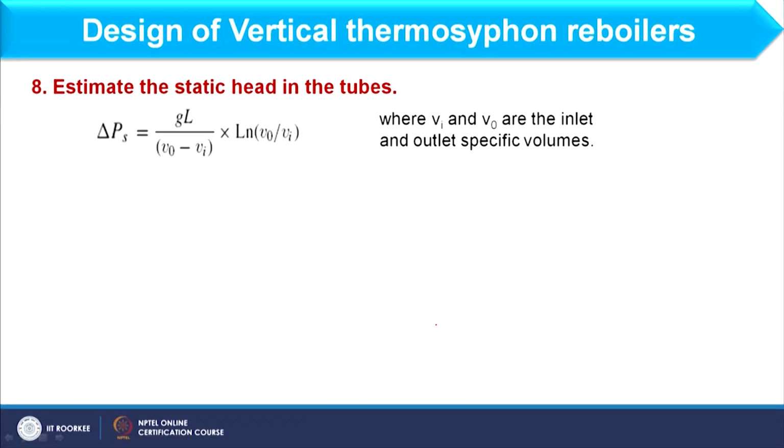And secondly, we should consider the pressure drop due to static head, because liquid will always be available in the tube side. Okay. And why have we considered the friction? Because that liquid vapor mixture moves throughout the length. Okay. So, as far as static head is concerned, we have the expression rho g L, fine, but here we are considering this differently because I have a different condition of feed at inlet as well as at exit. So, here we should consider specific volume instead of densities.